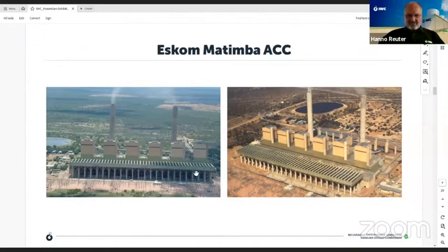The height of this platform is 50 meters above the ground. These fans have a diameter of 9 meters. If you think of an airplane, a Cessna 172, it has a wingspan of 11 meters. So in such a fan, we have 8 blades, almost like 8 wings of such a plane, rotating, and they are driven by 270 kilowatt motors. That means for the whole plant, we need about 70 megawatts of power just to drive the fans of this air-cooled condenser, which is effectively almost a full new renewable energy power plant of the kind currently being built, like Redstone, for instance.